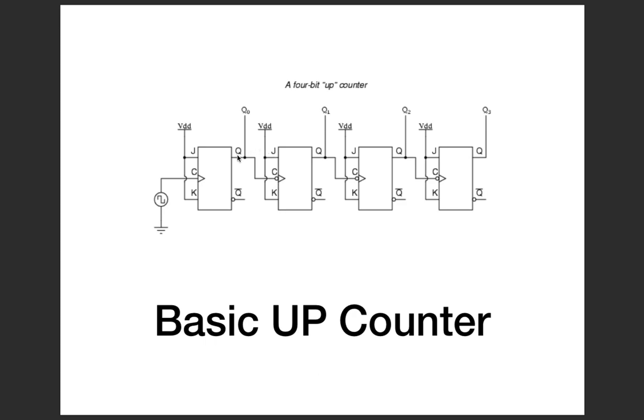And this is the circuit we built eventually. The first JK flip-flop will be triggered with the basic clock itself. Then in order to cut the frequency down and make sure that the next bit changes only when B0 falls, we have connected the Q of the first flip-flop with the clock of the next. Similarly we went on with this and we identified that Q0, Q1, Q2, Q3, or in other terms B0, B1, B2, B3 will follow the sequence from 0 0 0 0 to 1 1 1 1.